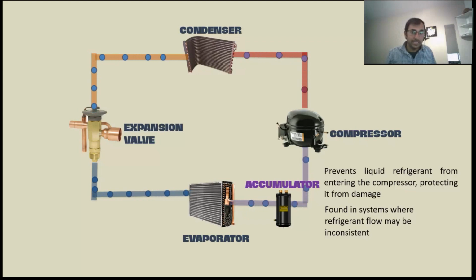And in case liquid refrigerant enters the compressor, it will be damaged. So that's why it is not allowable for any liquid refrigerant to enter the compressor. And this accumulator is a must for all types of refrigeration systems, especially for compressor driven, that is VCR.